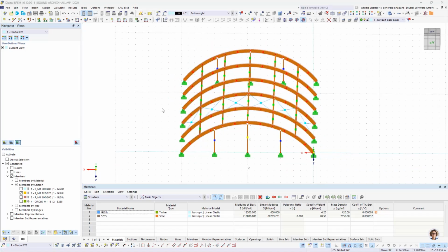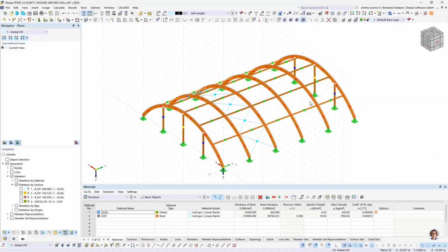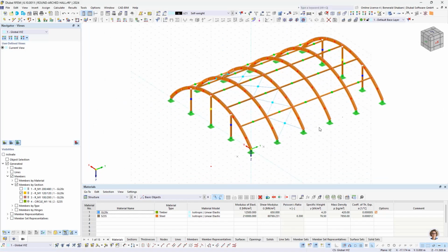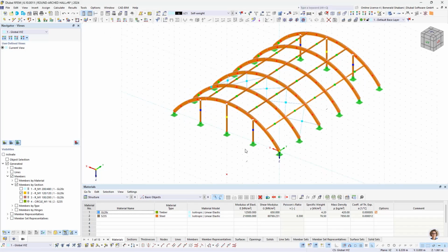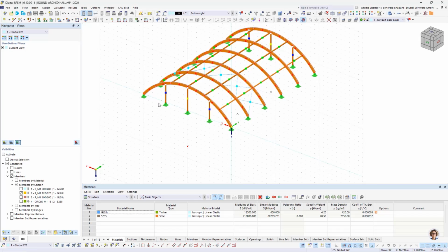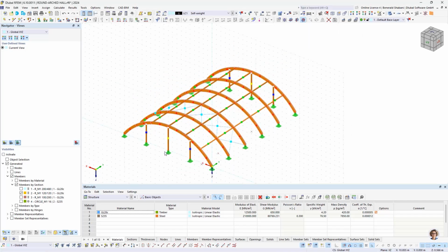Now we come to the second part of our webinar, which is also the last input. To proceed with that, I will firstly need to model at the gable supports 2 load transfer areas, which will help with the load transfer. They are probably the biggest advantage that we have today in RFEM and that we also use in our model.